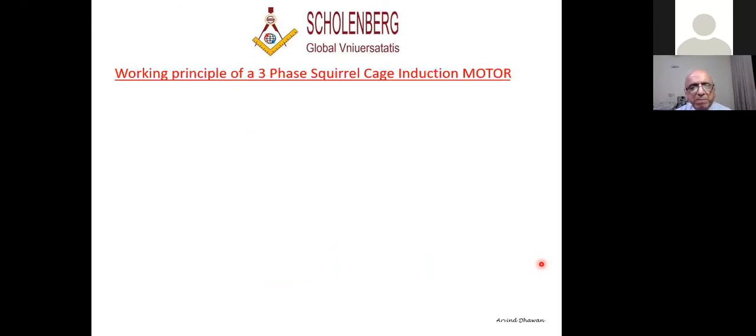Now let me explain motors. Every equipment, air conditioning, is all about motors. Compressor has a motor, blower has a motor, pump has a motor. Everywhere there's a motor, so you have to know how a motor works. What is a motor, right? Basically in air conditioning, we use 3-phase squirrel cage motors. But now with the advent of star ratings and saving on energy consumption, various types of motors have come into play, like BLDC motors.